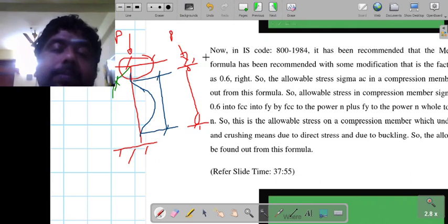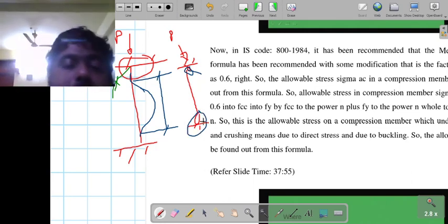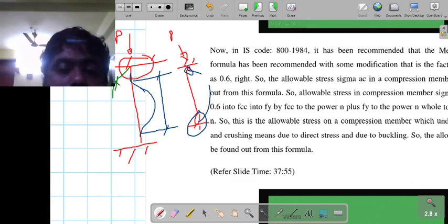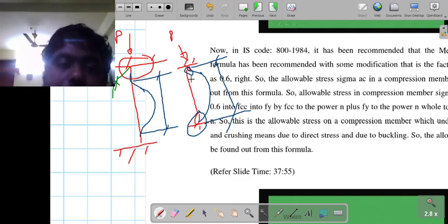Similarly, if you take this type of support, in this case if you apply the load, the column cannot go up and down, but the column can rotate, since horizontal rotation is not blocked here. So horizontally it is not restrained, that means it can start buckling from here. Since this is a support and a support also on the other end, this part can also end buckling. So if this is the shape of the buckling, the distance from here to here is the full length. So for this type of support, the effective length will be the full length, that is L. Okay, like that, depending on the other type of support.